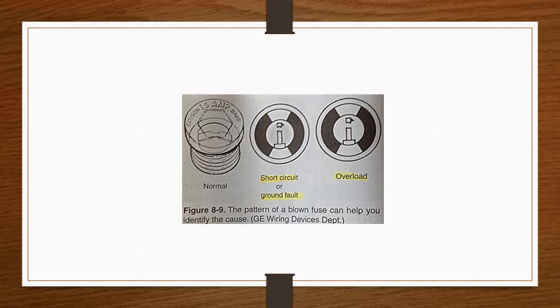2. Look for the source of the overcurrent condition. If you suspect a short circuit or ground fault, examine the switches and receptacles on that circuit. You may see a black charred area if the short occurred at a device. 3. If the fuse indicates an overload, look for outlets with multiple appliances, overworked motors, or plugged-in machines with an ampacity higher than the circuit's ampacity.